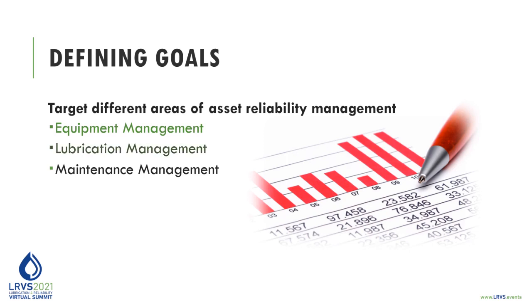The second thing is our lubrication management. What do we want there? We want to consolidate. We want to extend drain intervals or maybe optimize things like that. Get a better storage facility. Maybe with oil analysis, we could actually get a better understanding of how to utilize the data, make it more meaningful. And then finally, with maintenance management, what could that mean? That means trying to shift away from reactive maintenance towards a more progressive maintenance approach, where it's proactive.